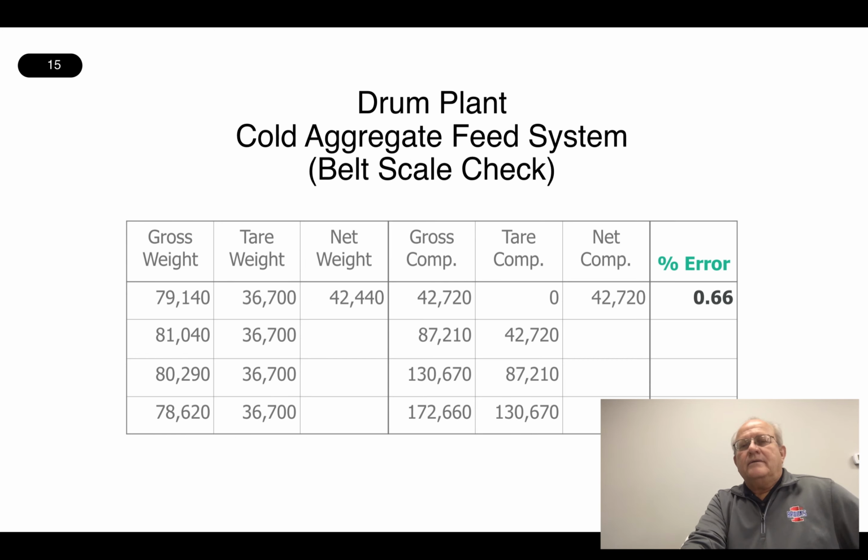Now, not bad for the first try of the season. You're close. At this point, you can either do calculations and figure out how to adjust your span values in your electronic scale conveyor, or with most of them anymore, you just tell it what the pounds error is, and it will do an automatic recalibration. So, you're off on the first one. Let's go again.